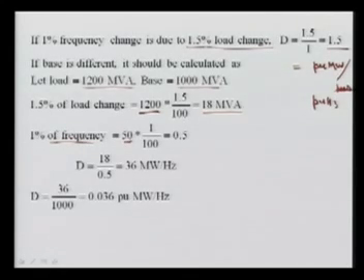So 1% means 1 upon 100. So we are just getting this 1% change means this much hertz. And if you are dividing here 18 upon 5.5, we are getting 36 megawatt per hertz with power factor as unity. Here the power factor we have taken unity.